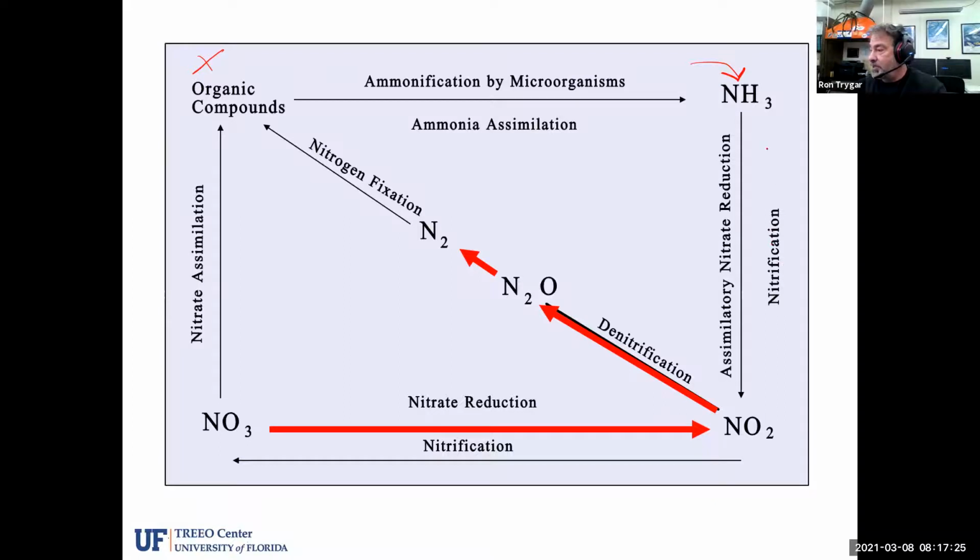And we nitrified, we kind of came this direction and we went to nitrification, and that took place in the aeration basins, and that was in an oxidative state. And then we did the process again, finished off the nitrification to make nitrate, which was the fully oxidized version of the nitrogen with respect to oxygen, 3 oxygens and 1 nitrogen atom, making a compound known as nitrate. And we called that nitrification. So that was all during oxidation processes.